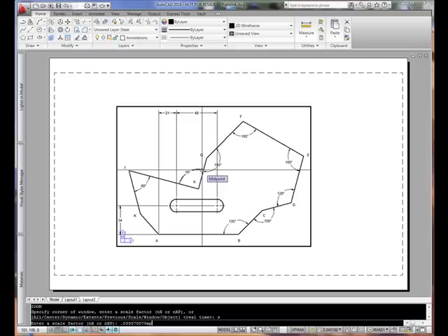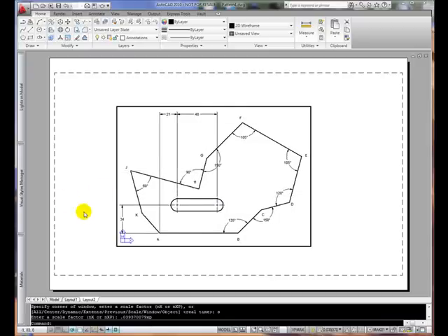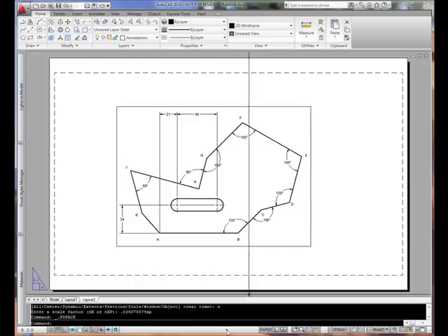Those numerals just happen to be 1 divided by 25.4. I'll press the Enter key, and as you can see, the zoom magnification changed ever so slightly. Now I'll click on the Model button so it'll change back to paper space.